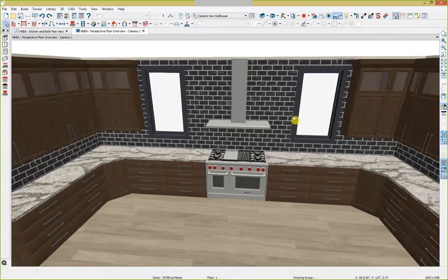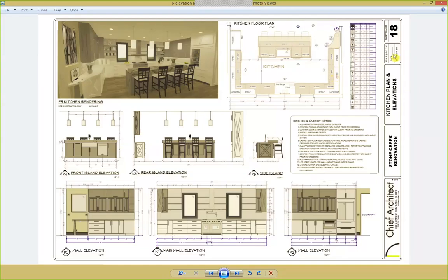So next, let's take a wall elevation of this wall over on the north side and then dimension it. If you take a look at a photo, the software can create layout sheets. We're not going to go through the process of creating the layout sheet in this demonstration in the essence of time. But here on the layout sheets, you can assemble your various elevations and notes, 3D views, floor plans, schedules, and so forth to create these layout sheets. We're going to be creating an elevation view similar to what you see here. So let's go ahead and get started on that.